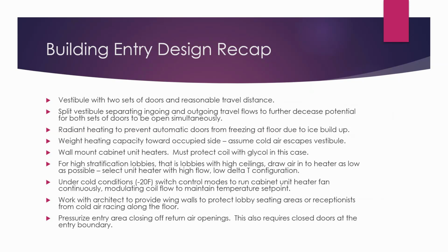Work with an architect to provide wing walls to protect lobby seating areas or receptionists from cold air racing along the floor. So just picture in cold climates, there's nothing you can do when the door opens. There's cold air that comes rushing into the building. Your heaters need to be configured to grab that air and turn it into warm air as soon as possible, but that takes some time, and there needs to be some distance for that.